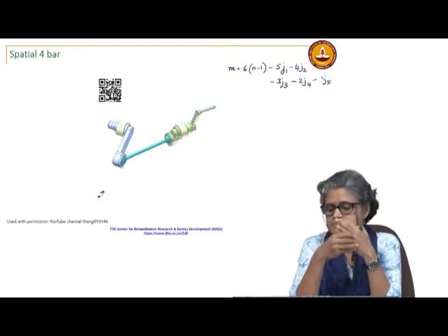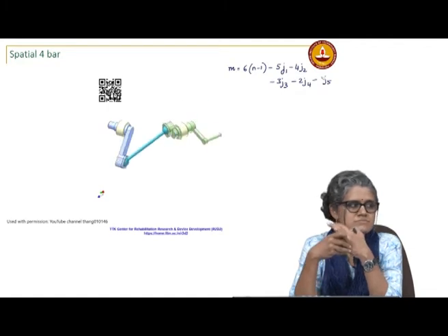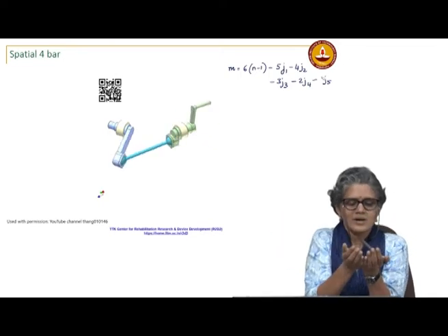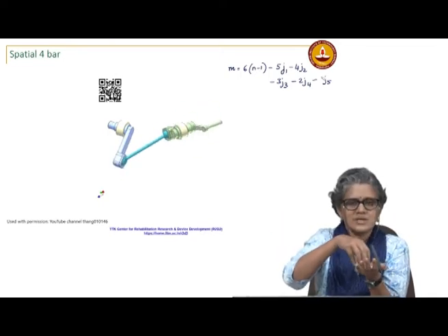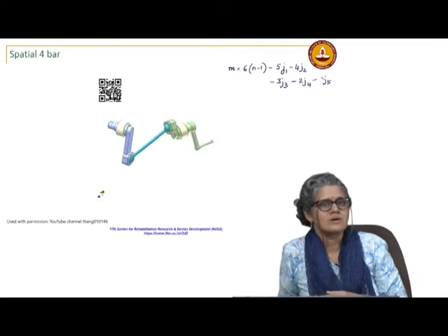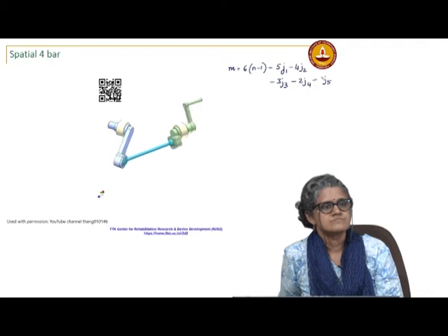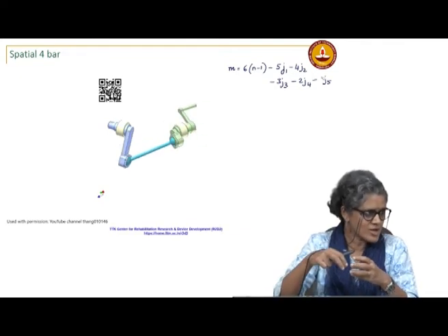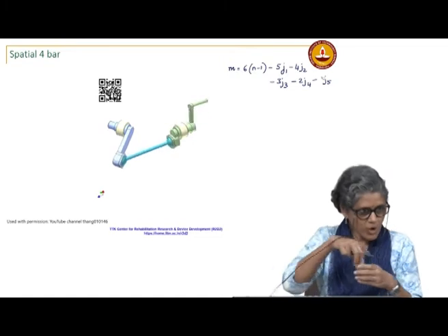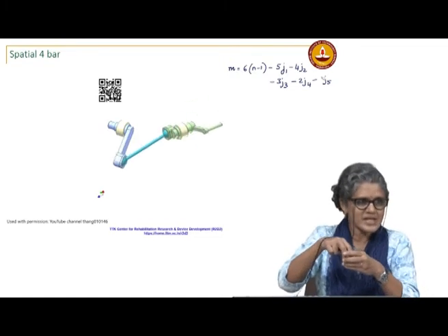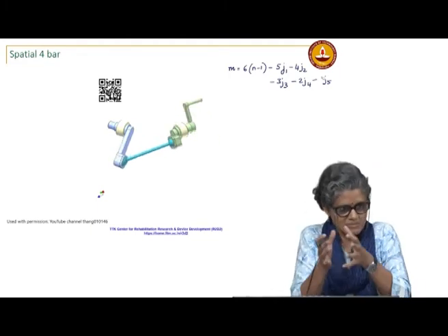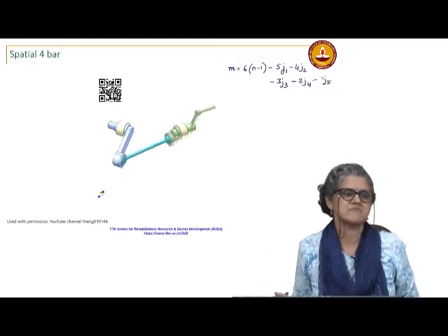Okay. In any situation, if there are 2 different directions which are going to allow the ball. So, it is like a planar joint. In one direction I can understand, as soon as I increase it to 2 directions of translation, the ball can come out. What if that itself can slide? So, the ball is in a slot. Understood. Okay. So, the ball can slide within that slot, but that slot can slide in another direction in the plane. So, that becomes a composite joint which has 5 degrees of freedom.